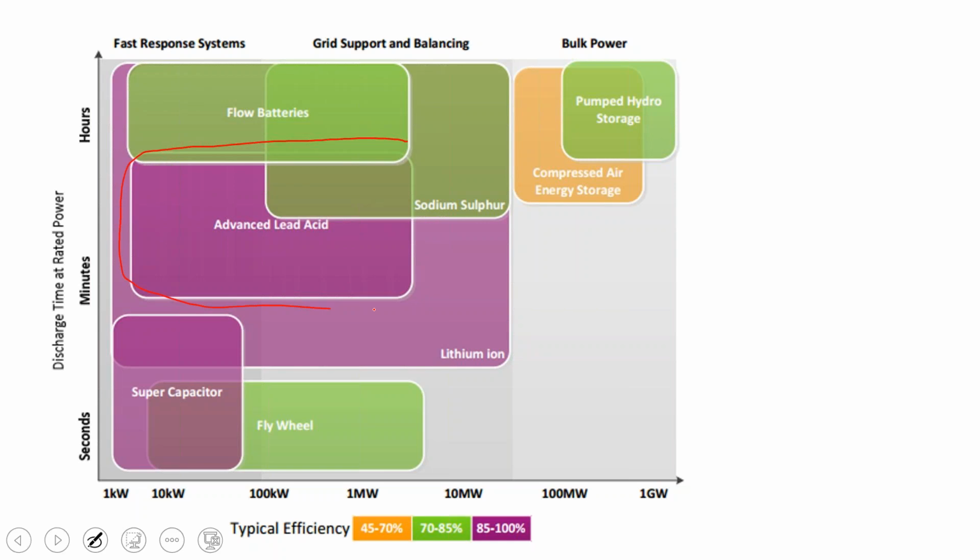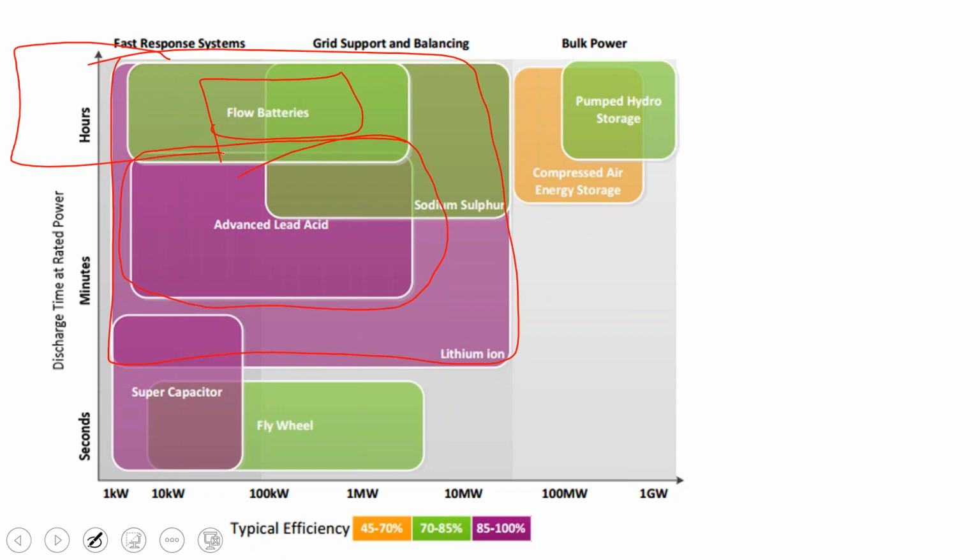This, I think, is a good chart to show you the capabilities of lead acid versus lithium ion and other kinds of storage technologies. There is another battery type called flow batteries, which is the next step in our march towards fuel cells. But the only flow battery company that I know of, Redflow, an Australian company, has announced that they're not targeting residential or commercial, and they're just going into utility scale. And that might make sense because, with utility scale, they know every day that the battery is going to be turning on at noon and operating towards 5 or 6 in the evening, and whatever it can outflow, it outflows, at a slow and steady pace throughout that time frame.